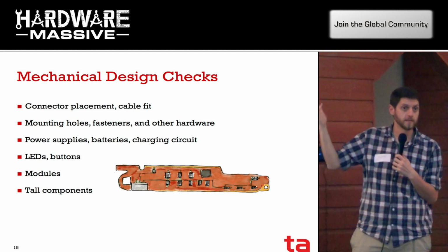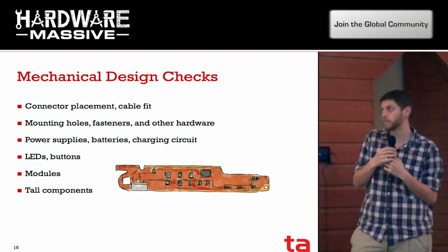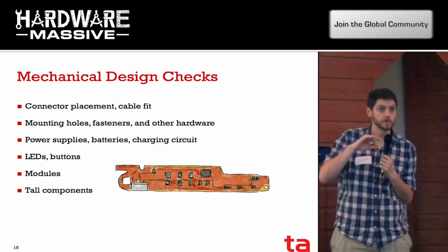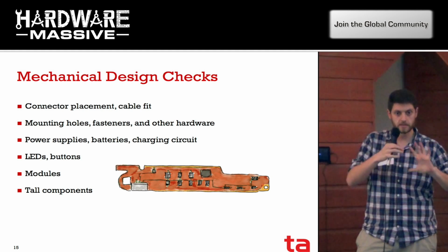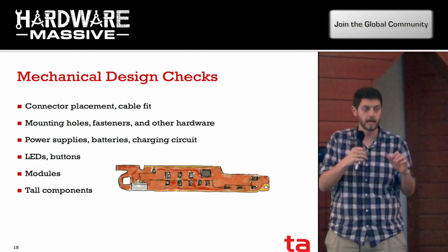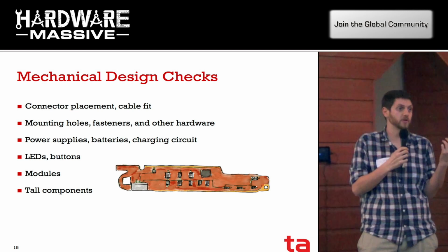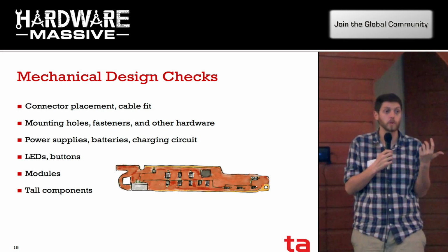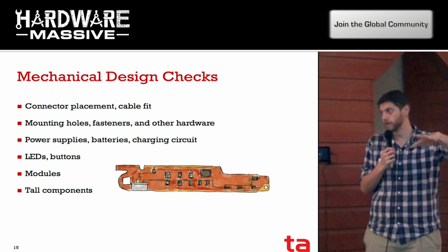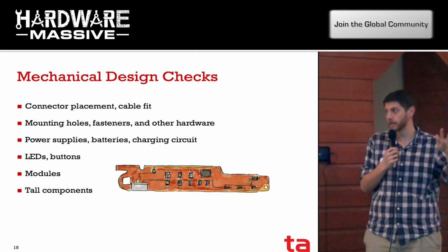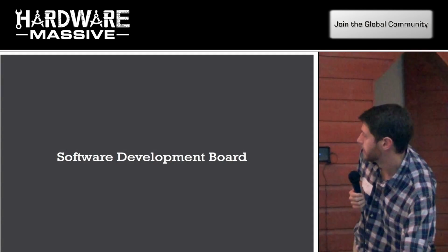So, in addition to some of the other things that you can validate that I mentioned before with this type of mock-up, there are connectors and cables. One of the fun things, particularly when you get into wearables or devices that have many different boards that are hooked together, is routing the cables and the connectors. It can be an afterthought, but oftentimes people are very sad when it is. Make sure it mounts to everything, all the circuits, the power supply, the batteries, all that type of stuff works.